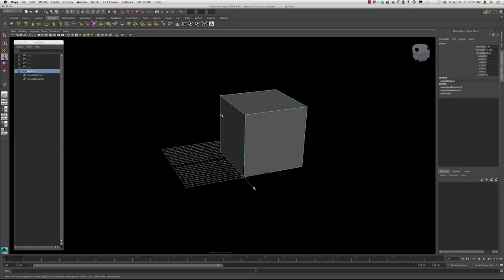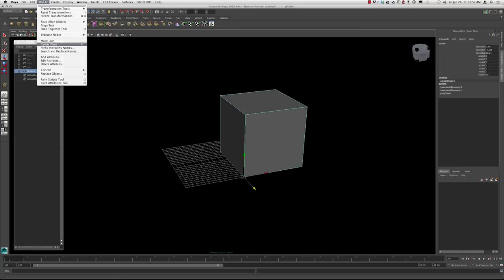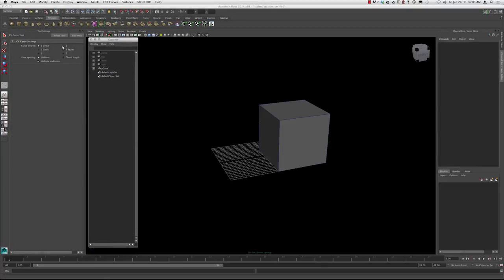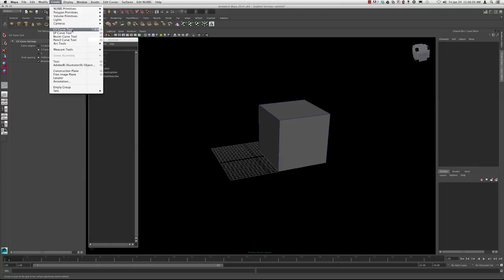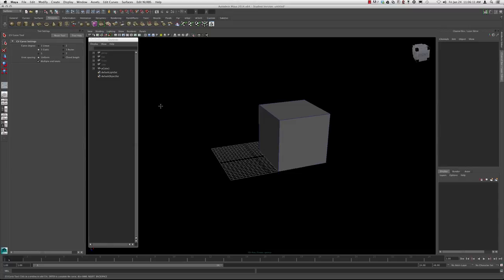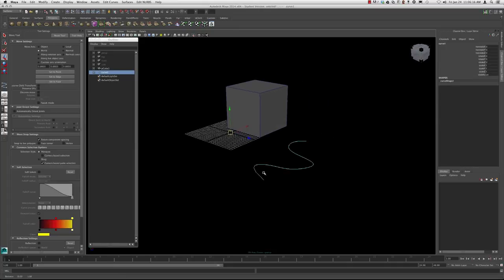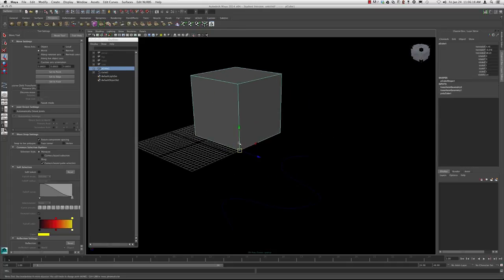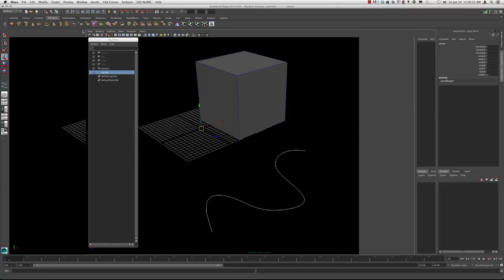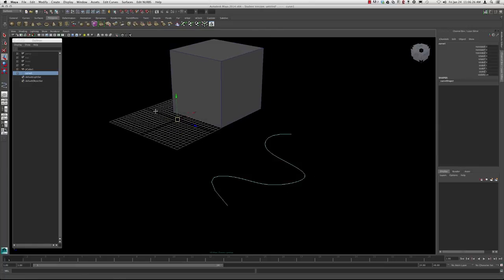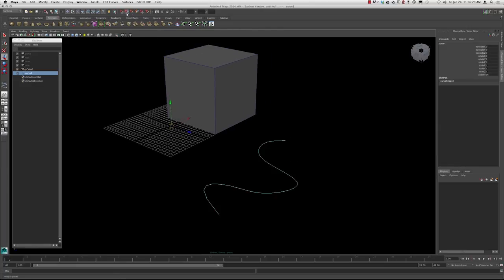Same thing with, there's a curve snap as well. And we'll talk about creating the curves later, but I'm just going to go ahead and show you this now. So I went to the create curve tool. I opened the dialog box, specified the degree, and I'm just going to draw this. Don't worry about getting the specifics of that. And if you wanted to snap to the curve, then you would need to go to the curve snap, which is right here.